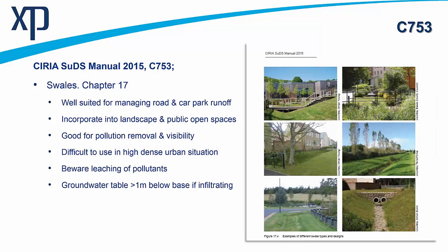Plus, you need to be careful of the groundwater table to make sure it is at least 1 meter below the base, not just of a swale, but of any infiltrating structure at all. But there's some really good examples to see within the SuDS manual, so I'd encourage you to get that and have a look. Where you do have steep sites, there are workarounds, as I mentioned. We'll look at some more shots in a minute, but we could put in larger stone riprap, gabions in the invert. This has been used successfully in some sites that I'm aware of to reduce the risk of that scour.